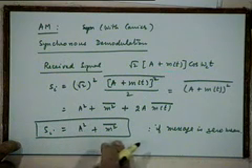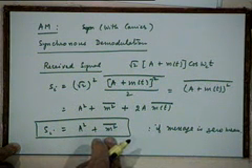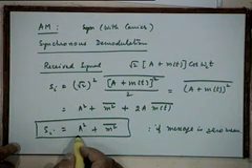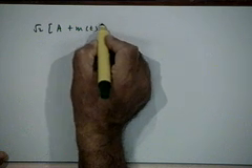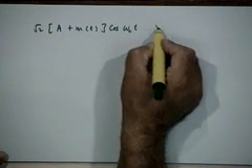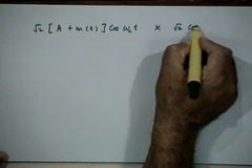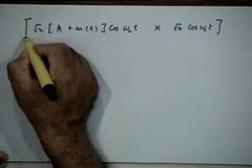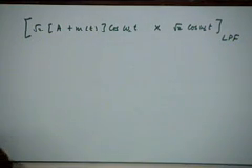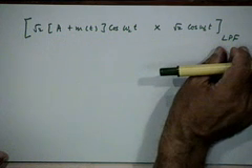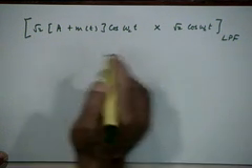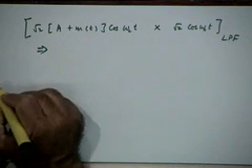Now this is different. It is no longer m squared bar because you are also transmitting some carrier. What is your demodulation process? Once again, this root 2 into (A + m(t)) that you are receiving, you are going to multiply this with, let us say, root 2 cosine omega_c t, and the result will be low pass filtered. These are the operations you are going to do for demodulation. Multiply by root 2 cosine omega_c t followed by low pass filtering. What will result? What will be the demodulated output?